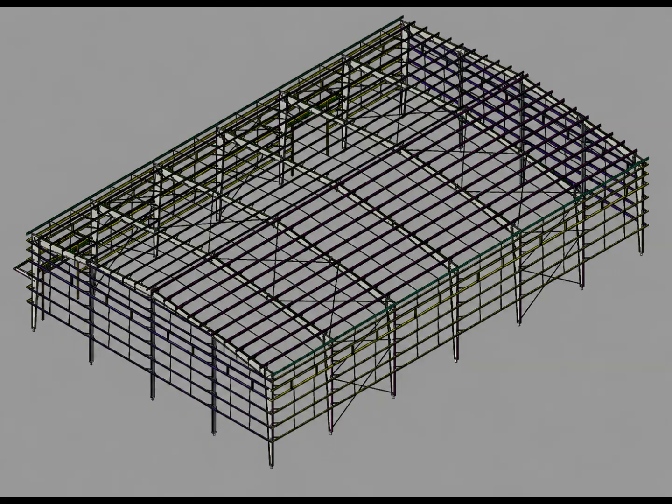So, instead of seeing a sag rod as just a small line in a drawing, we can now understand that it is one component within a much larger framing system. The same approach can be applied to purlins, girts, bracing, columns, rafters, eave members, and connection components. First, identify the member in the drawing. Then understand its location. Then understand its connection. And finally, see how it fits into the complete 3D structure.